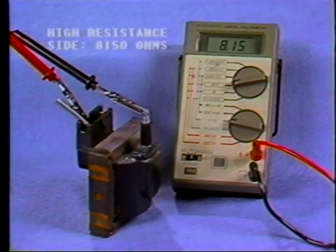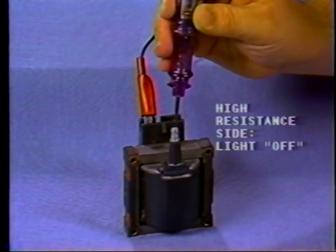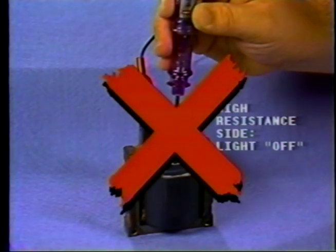When the open component or conductor is tested, the ohm meter will indicate infinity, or the test light won't light. While the ohm meter can indicate the amount of resistance of components being tested, the self-powered test light cannot. If you're testing components designed with high internal resistance, the self-powered test light may not light. Therefore, testing these components with a self-powered test light is not recommended.